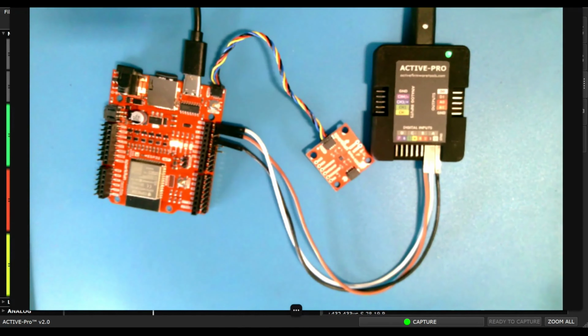And as you saw on the I2C bus, it gathers the sensor data over the I2C bus. It takes the magnitude of that, which is x squared plus y squared plus z squared, and compares it against the threshold. If it's bigger than the threshold, it will send a string, ESP32 followed by the actual hit number, out the BLE module to the other side, to the sensor hub. So this is the application. This is what we captured on the I2C bus previously. But what we're going to do now, instead of capturing the I2C bus, is have this firmware output some data for us.